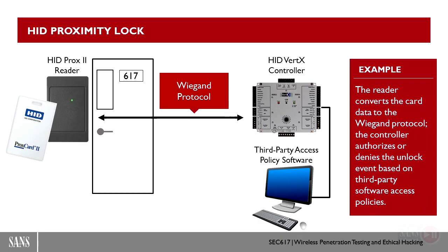have tamper detection. But for every one of the readers that I have encountered, the tamper detection is ignored because the tamper detection is not triggered via the Wiegand protocol. The tamper detection is triggered via another set of dry contacts, another wire itself, so outside of the protocol. And some of them have like a tilt sensor. Another one will have a light sensor so that when you pull it off, all of a sudden it sees light or the light changes. So it can trigger a tamper event.